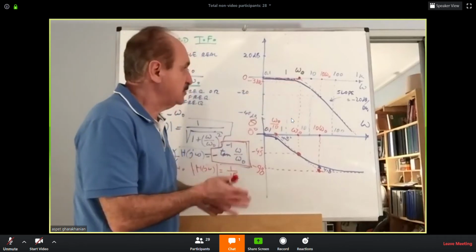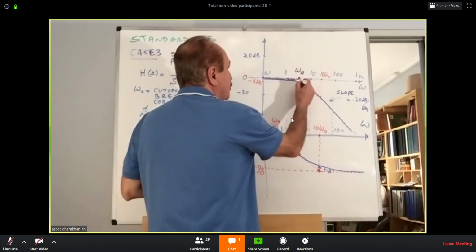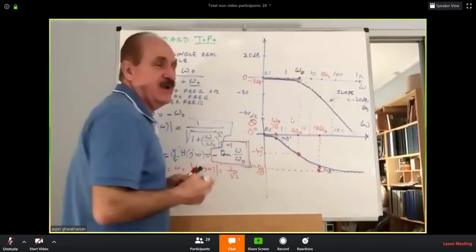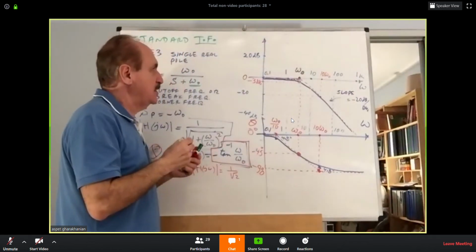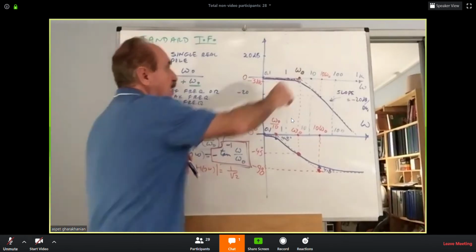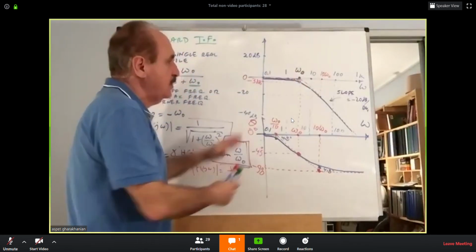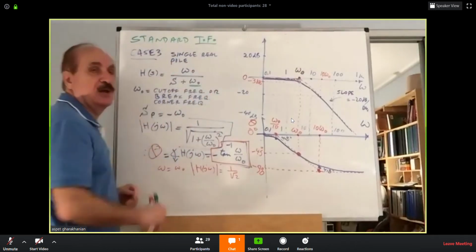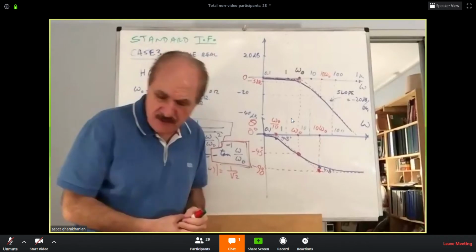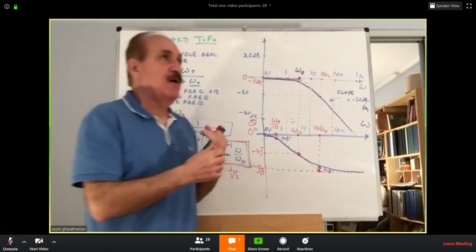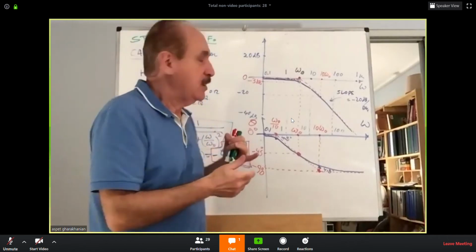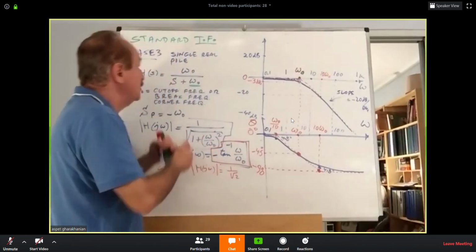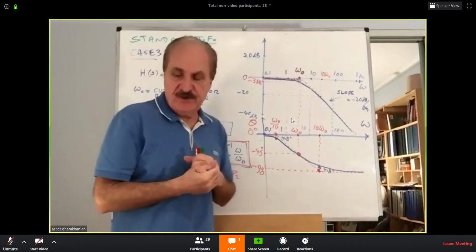So this spot is truly 3 dB under the break point, just slightly under the 0 line. And then you will construct the Bode plot of a single pole. Okay, so that was our case number 3. Now, case number 4, which is a zero. I'm going to construct that for you.